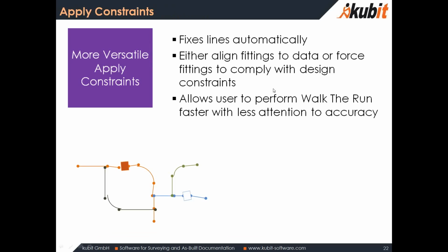Just a little review here, a middle step in order to get to your end deliverable. Apply Constraints really hasn't changed, but it really didn't need to be, honestly. I just want to explain its job is essentially to take all these fittings and these patterns that we found, take their center lines, and then make them coaxial and make them comply with design constraints.